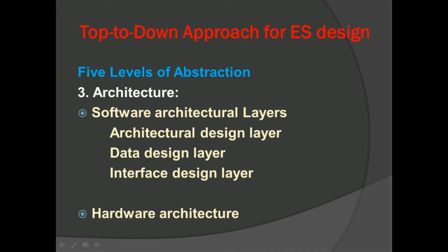Now the next layer talks about the interface design layer. The important question at this stage is, what shall be the interfaces to integrate the components, right? What should be the interfaces in the design? We talked about the engine control unit in our last lectures, and we have seen that to communicate between one module and another module of the same system, we are using CAN bus.